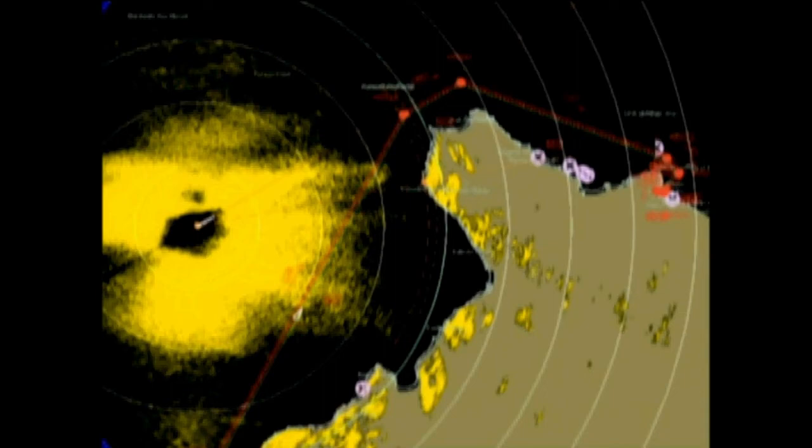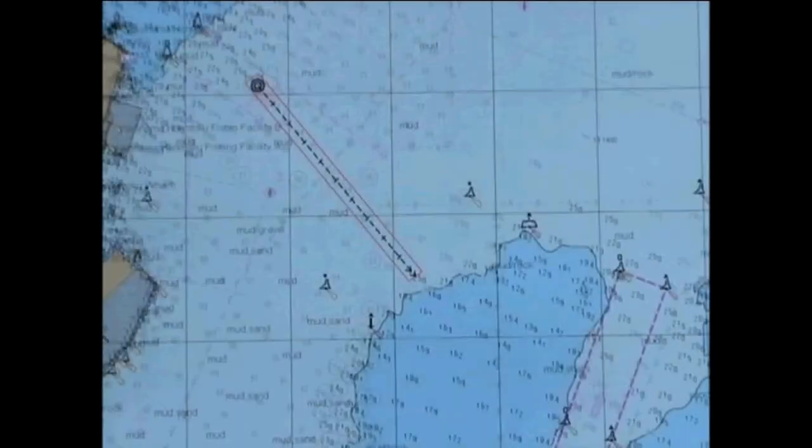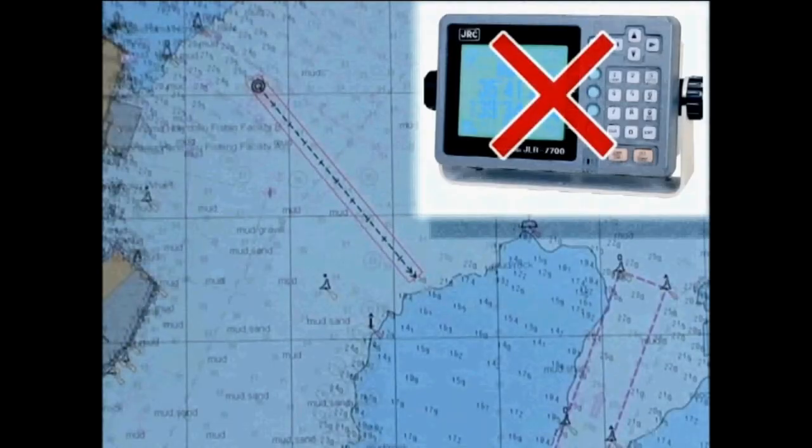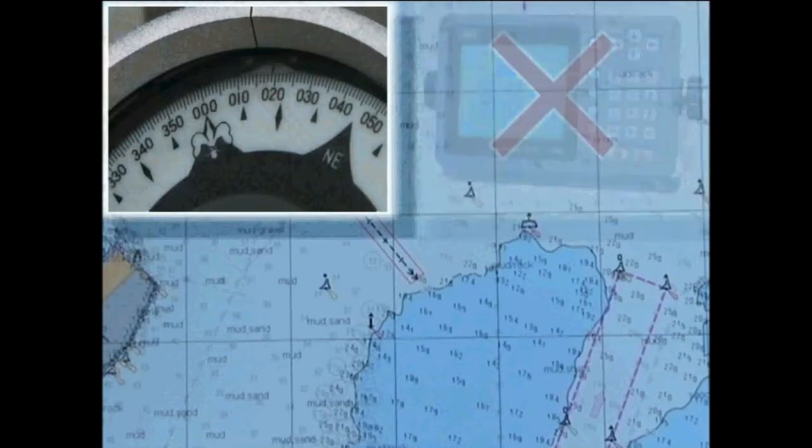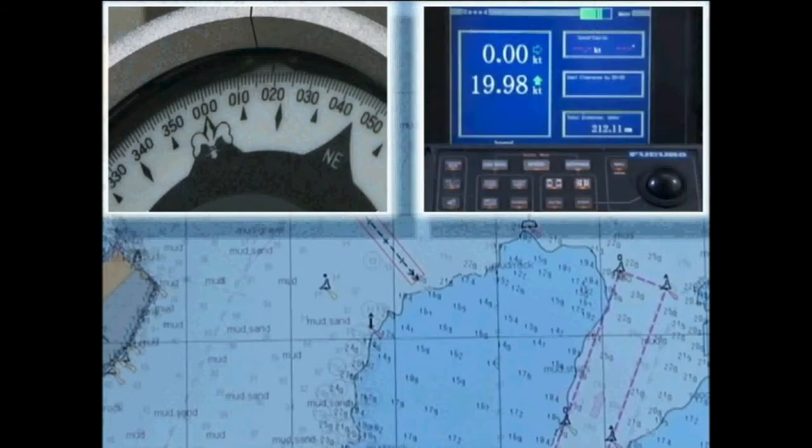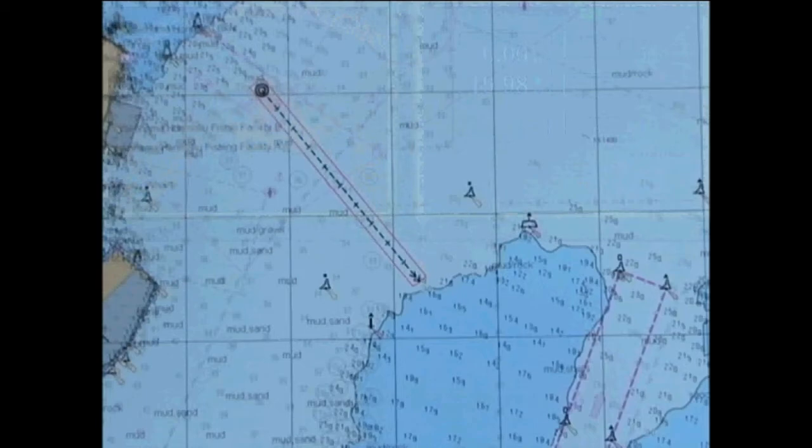Here are some points to remember when using ECDIS. When the radar image is superimposed on the ECDIS, the coastline of ENC and that of the radar image do not necessarily match. A ship positioning alarm sounds when a signal from an electronic positioning system like GPS is intercepted. As an alternative means, ECDIS can use dead reckoning based on calculations from the gyro compass and log.